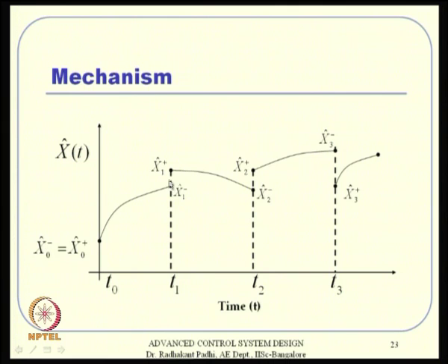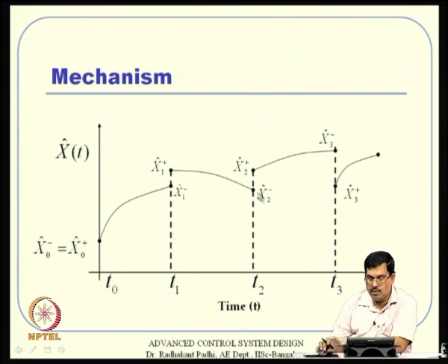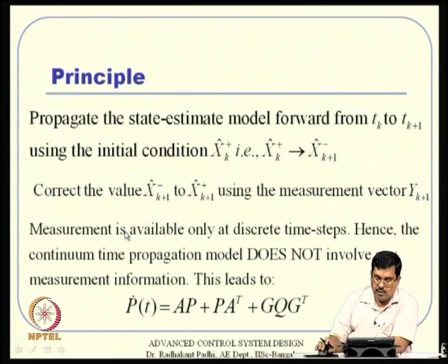Assuming the sensor gives me correct information, I can take advantage of that, and say, okay, I am already here, but let me correct myself a little and then operate further. So, this is prediction, this is correction, again prediction, because in between I do not have any sensor information, I have to simply rely on what I have. Starting with this initial condition, I will be able to predict, but at T2 I have got sensor information again, so let me correct again from here. Like that it will proceed.